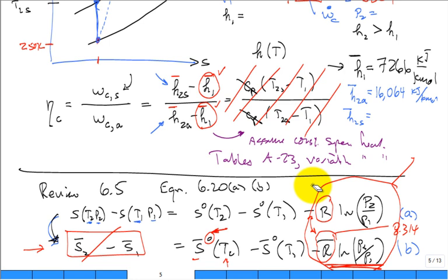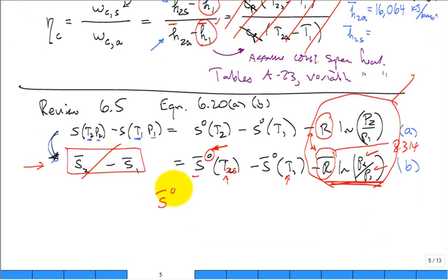Okay, so using this, what you can do is say this is T2s that I'm trying to calculate. I know the starting temperature. I know the final pressure. I know R bar. Guess what? I look up S naught bar. No, I'm sorry, I calculate S naught bar. True? Somebody did this correctly. Isn't that who showed me their number? Isn't that what you did? The intermediate step is you calculated S bar naught. What was that equal to? S bar naught of T2s is equal to S bar naught of T1 plus R bar natural log of P2 over P1.